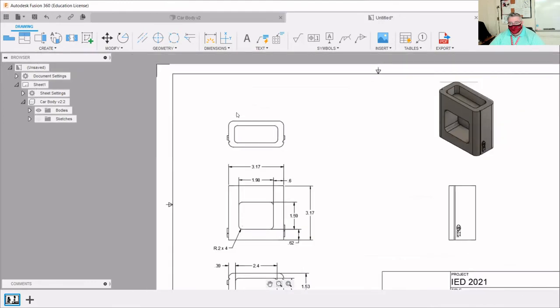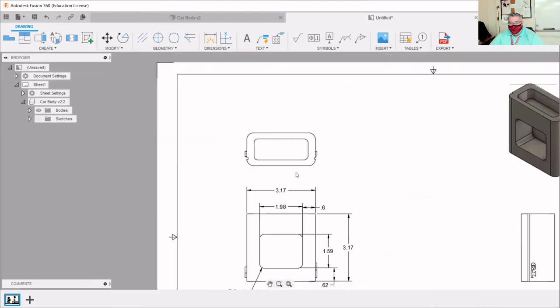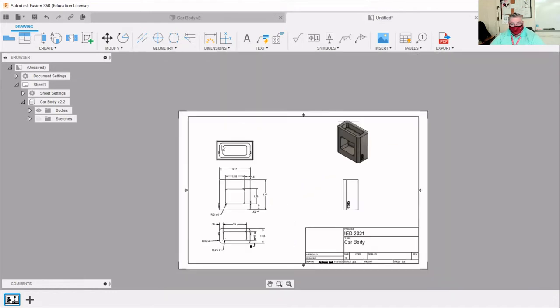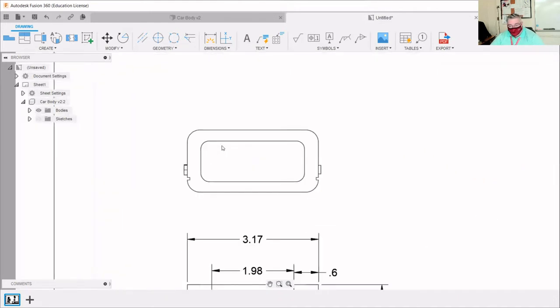All right, so now we're ready to do this other part. Same idea. So whatever we had down here, we should also have up top, with the exception of the external fillets. We don't have to label the external fillets again because they run the entire length of the part. So the external fillets, we don't need to dimension, but the internal ones we do.